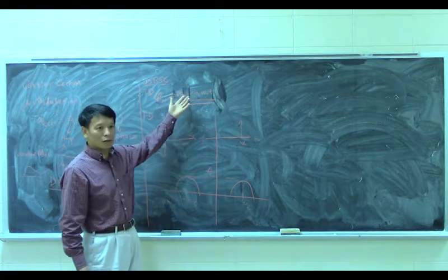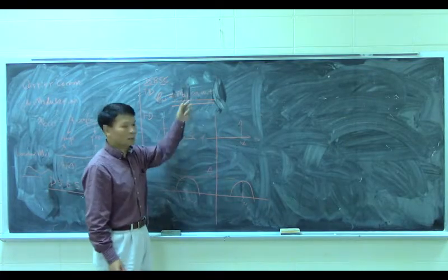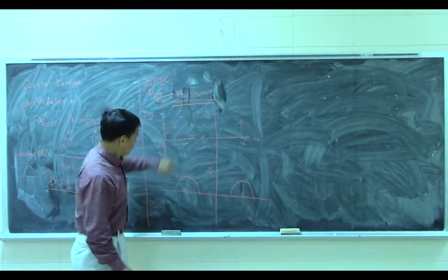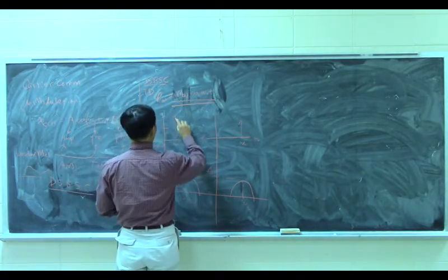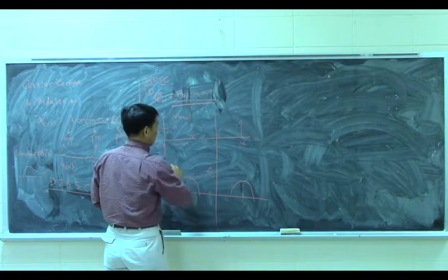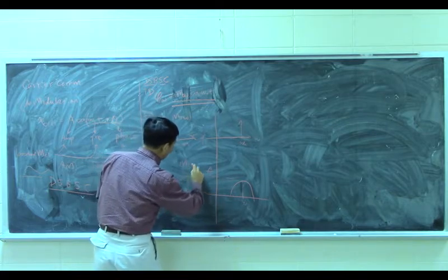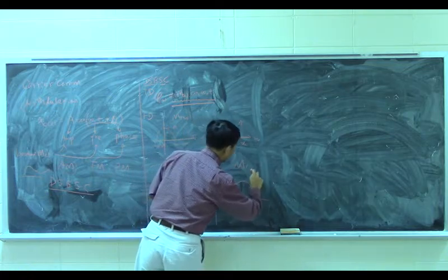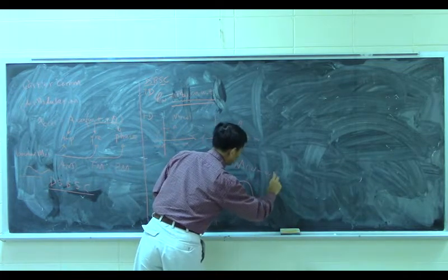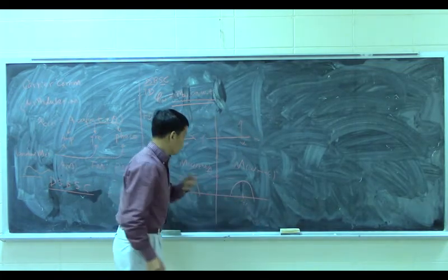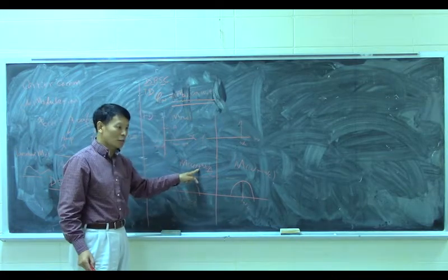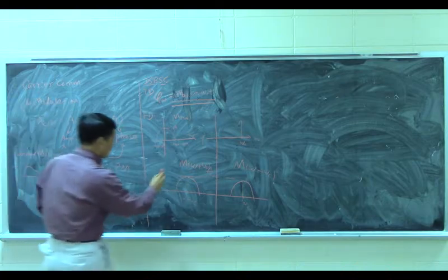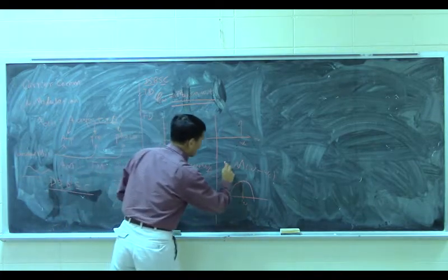Just the Fourier transform of this multiplication. If you still remember in the table, this one is a capital M(omega). And so that's why it will be capital M(omega plus omega_c). This one will be capital M(omega minus omega_c), centered at positive omega_c. This plus omega_c will be centered at negative omega_c. And the amplitude will equal half here, and this one also equals half here.